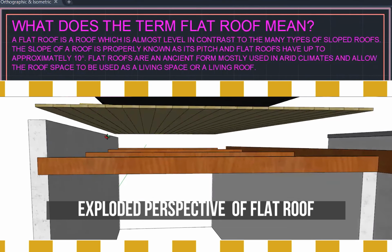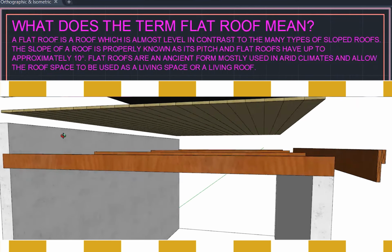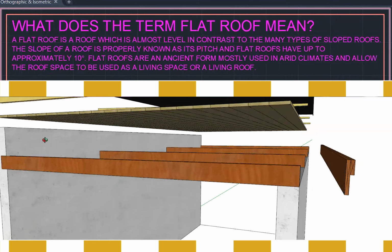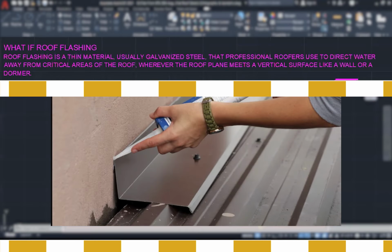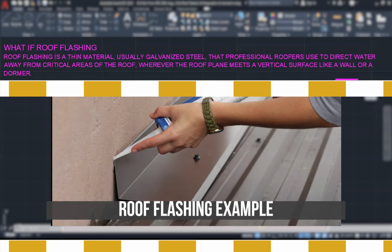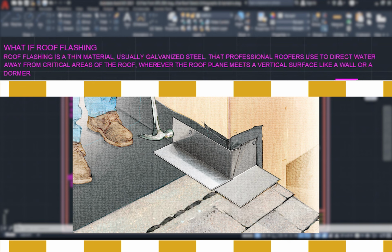Now, there's a term that you would hear me use, which is called roof flashing. So what is roof flashing? Roof flashing is a thin material, usually galvanized steel, that professional roofers use to direct water from critical areas of the roof. Wherever the roof plane meets a vertical surface, like a wall or a dormer, that is where a roof flashing would be used.